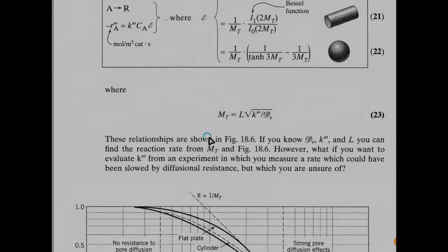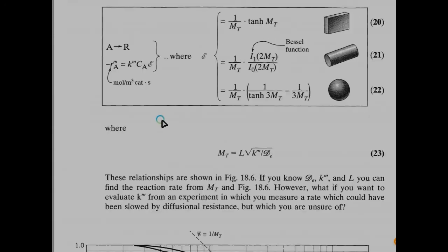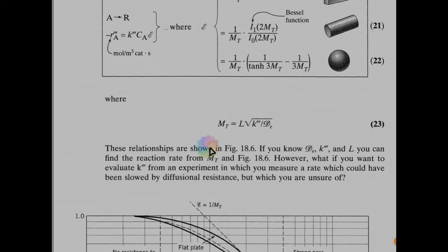In this chapter, as in my design of the acetylene reactor, the case considered is one in which the catalyst has no diffusion, that is, the catalyst is non-porous. But if you have a catalyst with a porous surface and some kind of diffusion, you have to find the effective rate constant, because the reaction is also taking place inside the catalyst pores. So the change will be based on the Thiele modulus.